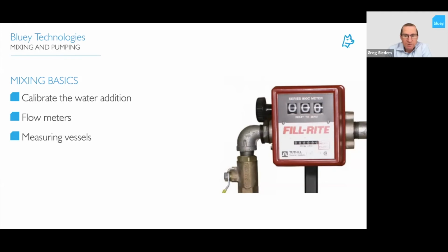We always get calls from people on site saying that your grout hasn't achieved strength. We go out there and double check. The first thing we want to do is check the calibration, how they're adding the water. They say they're putting in 4 litres, you check the calibration, it could be putting 5 or 6 litres in there. So that'll have a huge effect on the strength gain of the product and the performance.